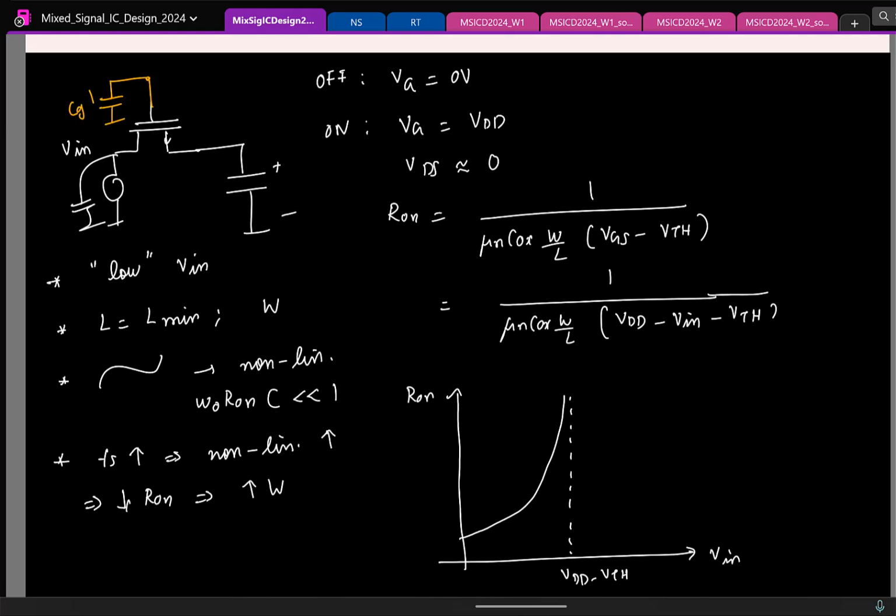So let's say the gate capacitance increases, what's the issue? Slower? Can you explain? While applying the signal at the gate, it will take time. Yeah, so as he's pointing out, remember that I have to feed in a clock signal to the control terminal of the switch.